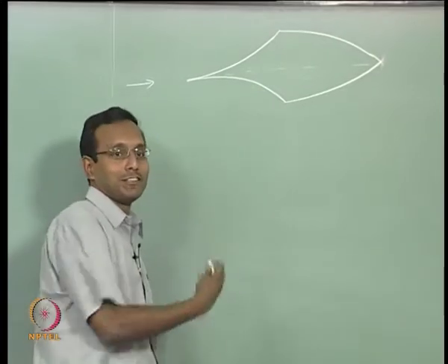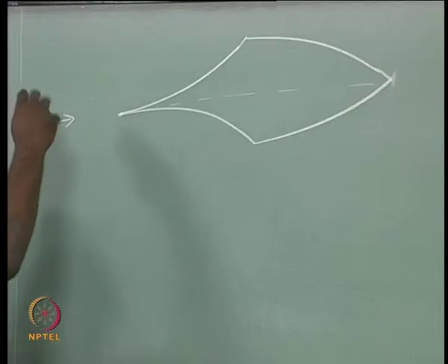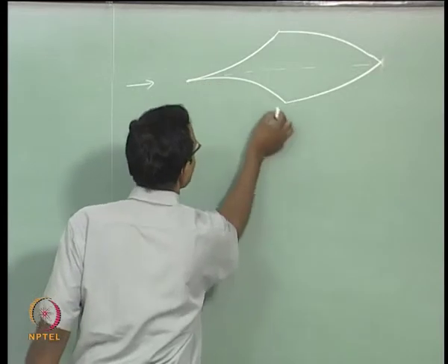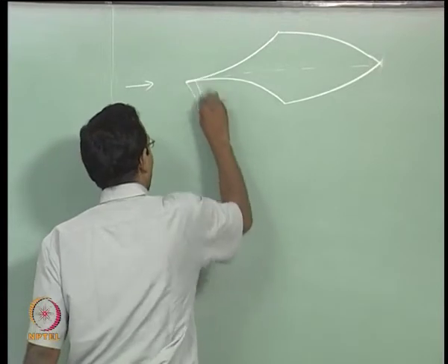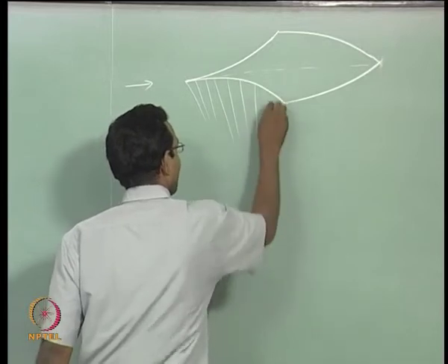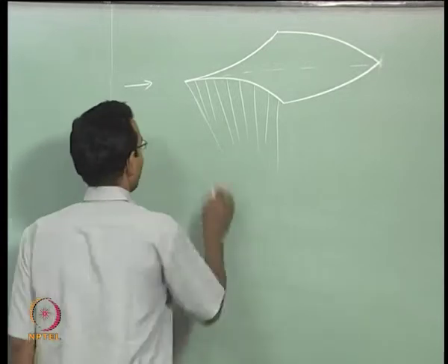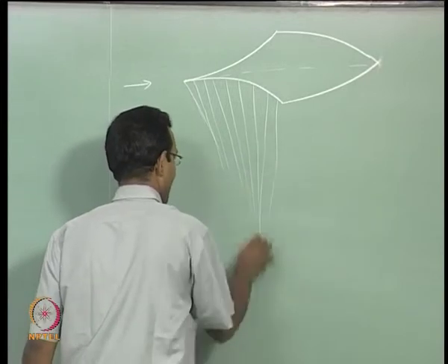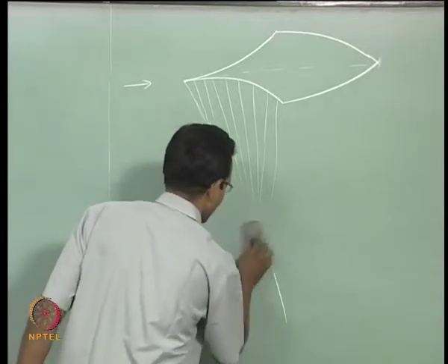Again I am going to use shock expansion theory here, the craziest airfoil. Since I am saying it is symmetric and I do not have top space in the board, I will look at only the bottom. It is a smooth corner transition, smooth compression. So, I am going to have a set of Prandtl-Meyer waves which are coming out from here, and I already told you that these waves, since they are all compression waves, they will all get together eventually to form a shock here. But let us not worry about that right now, it is not coming from shock expansion theory.